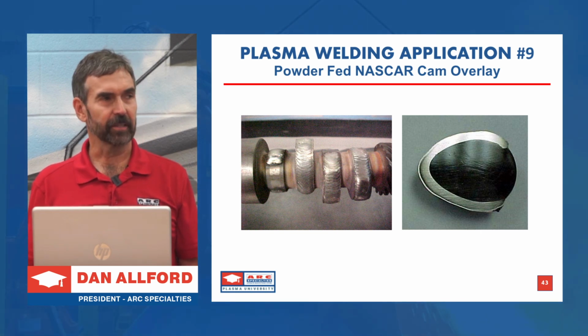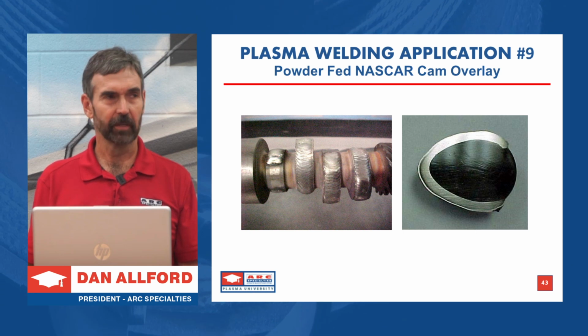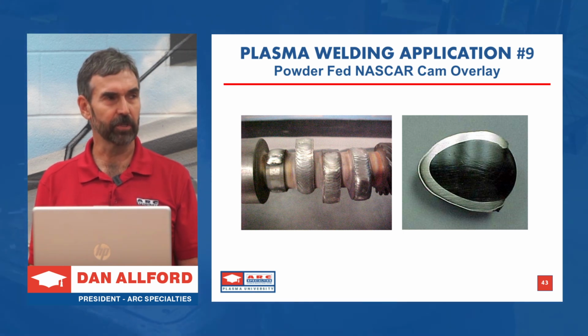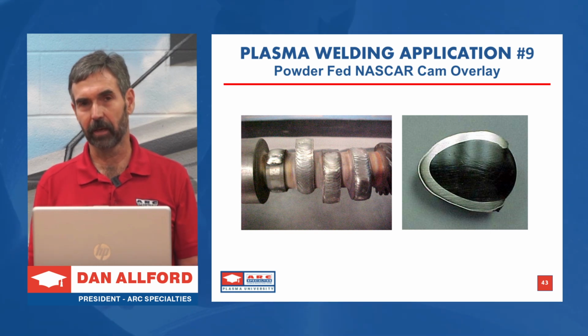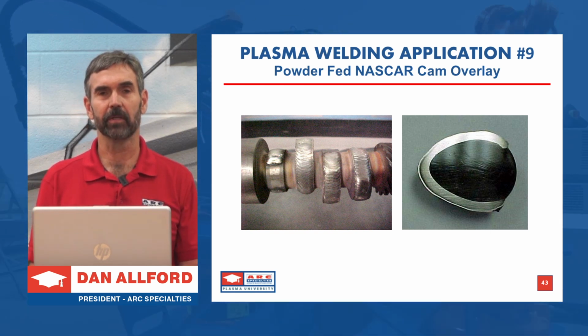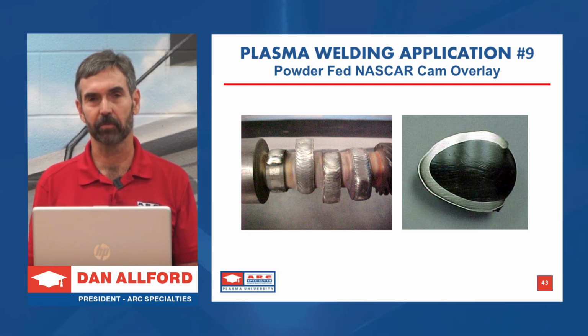NASCAR has an interesting technique. A few years ago, they were lofting the tappets. That means the valves were floating. But as the team crew chiefs told me, you don't float, you don't win. But when the tappet landed back on these cams, it needed some place to land that was hard enough to take the blow. And so we were welding these camshafts with plasma.